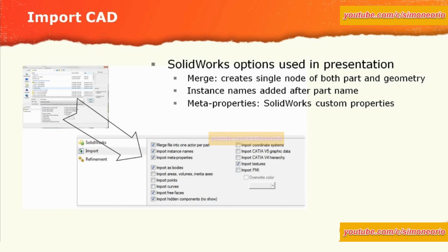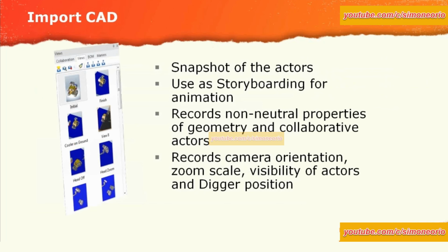You can decide if you want your instance names brought in. And then the third one is import meta properties. These are the SOLIDWORKS custom properties that you may be familiar with. You can bring those across as well.